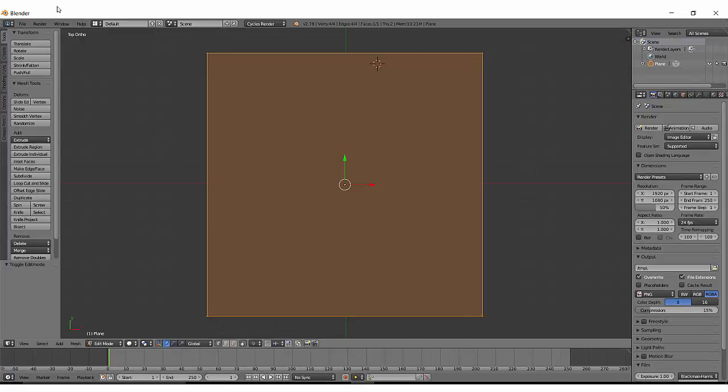Now after changing the view of your mesh to the top mode and setting it to orthogonal, if you press Tab, the whole plane is going to be selected. Plane in the sense of the mesh we have placed before. This indicates that it's in edit mode. You can toggle with the Tab button in order to switch between edit and non-edit mode.